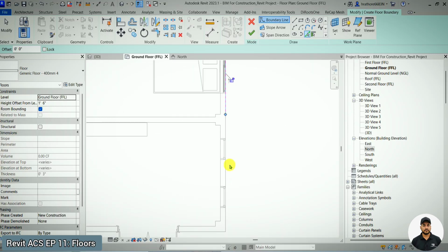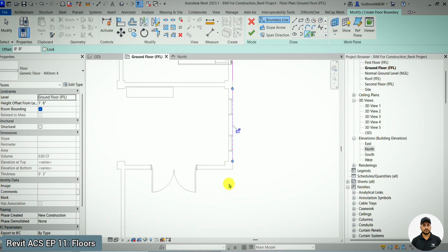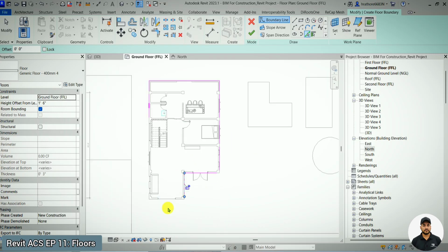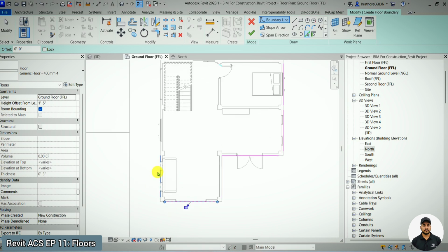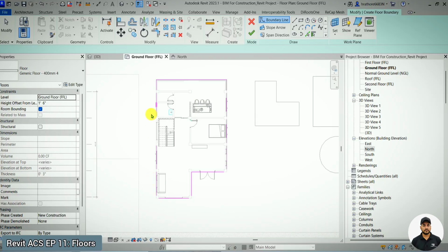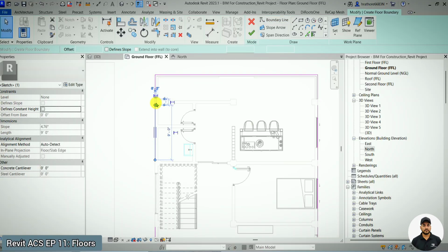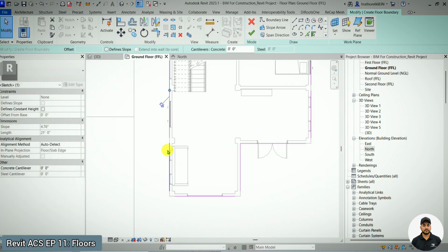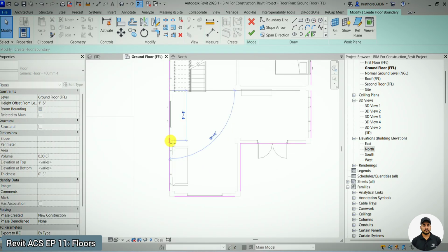Right now we have so many elements like doors and columns in between, so it is dividing all those lines as per the elements. That's why we have to choose multiple picks. But if you are clear, then use shortcuts to create geometries, then join them. You can use the TR command also to join corners.